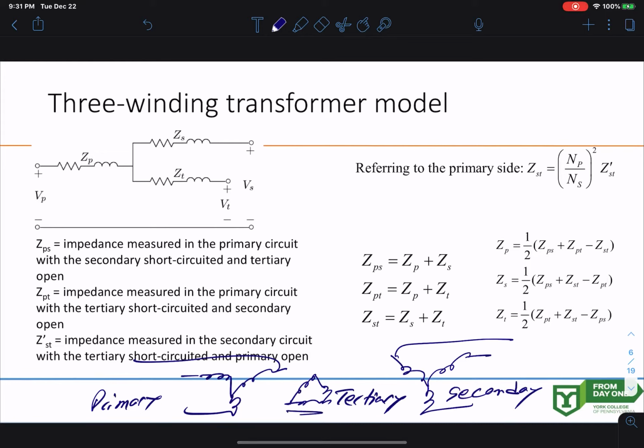Right? Why is this? This tertiary transformer is sometimes used for two reasons. One reason is to reduce or cancel out third harmonics. This delta connected transformer does not have any third harmonics. If you add all the third harmonics, they can become zero for a delta connected transformer.